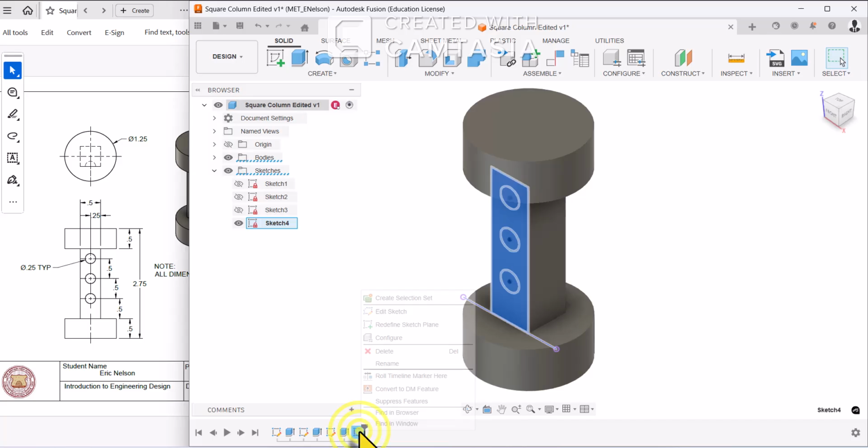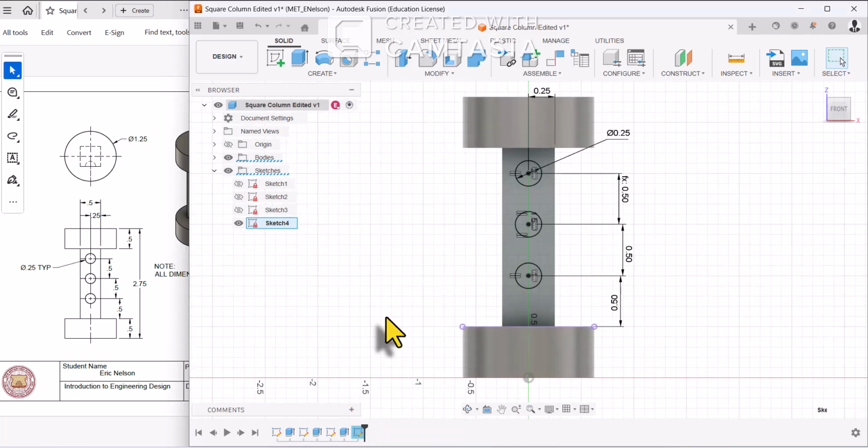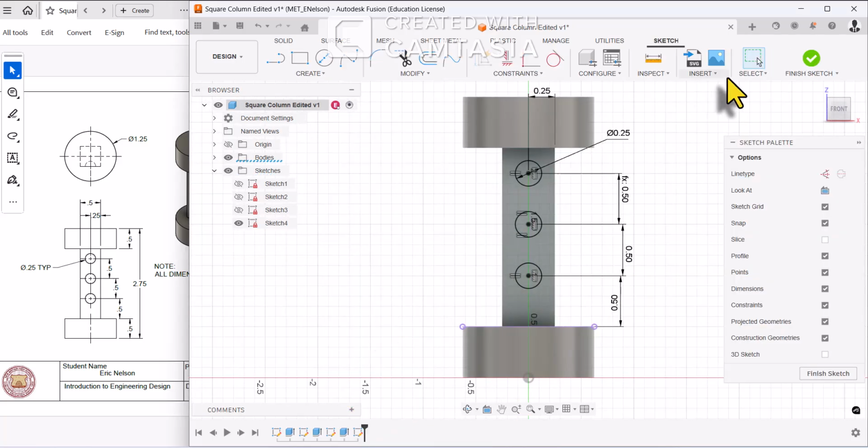That's this one, and we're going to edit it. First thing I want us to do is hit the button to make it a construction line, then choose line. And if you're going over, you see how it snaps in and I have that blue triangle right above? Click here and go straight down until we also have the blue triangle snapped in at the bottom. Right click and press OK.